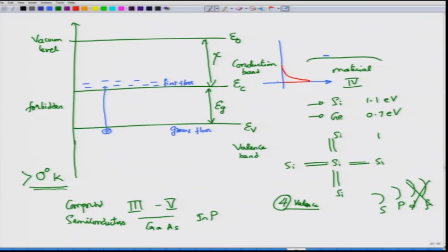Okay. So, this is what you would see when the temperature is greater than 0 degree Kelvin, and the width of this is roughly 2 kT, where T is the temperature of the material. Now, because there are electrons which have been moved up, there will be holes. I am showing these holes as uniform, but it is not necessary that they are uniform. The electrons may jump from any point here. So, they are not uniformly distributed, but for our representation purposes we have shown them to be uniformly distributed.